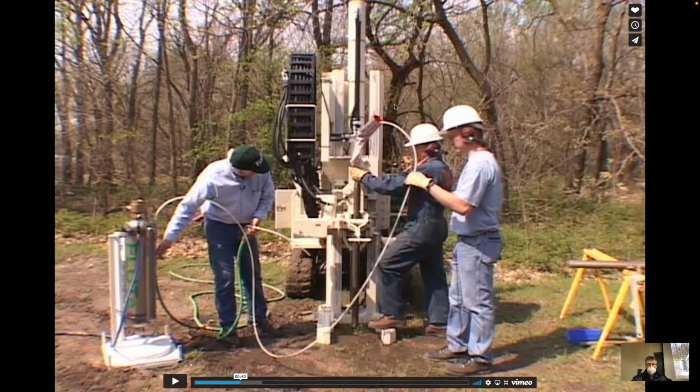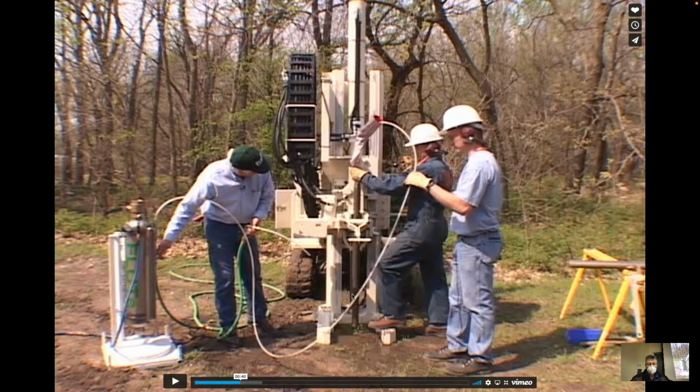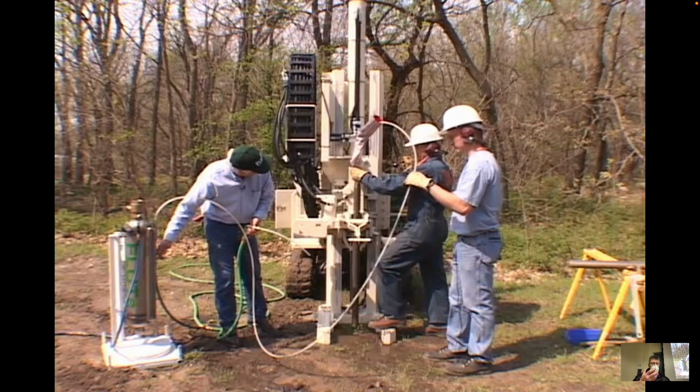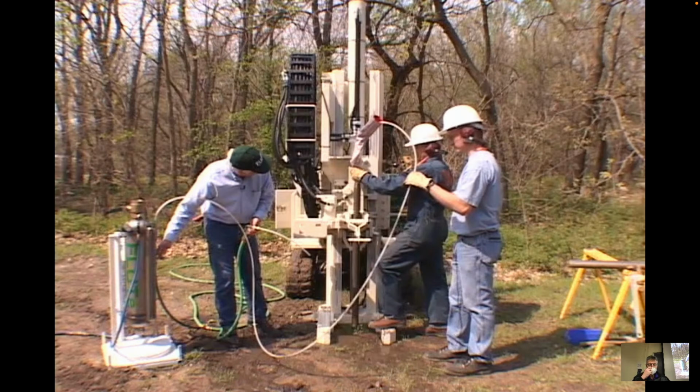So the idea is that it comes on a tractor, it just pushes rods into the ground. These rods have a conical tip, so that it makes basically a borehole that is kept open by the rods, which are the borehole wall, and allows you to then advance things down to the bottom of it, such as these piezometers that measure pressure, but also have, in this particular case, some kind of skin on them, which is reactive to whatever fluids it comes in contact with.